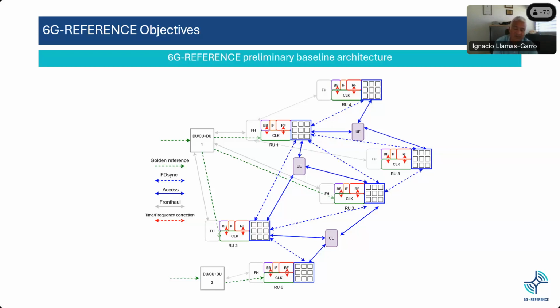Case 3 corresponds to radio units 2 and 6 at the bottom of the figure that coherently transmit to one user but are attached to different central units, which may happen often in a densified cell-free deployment. In all these cases, the aim of synchronization mechanisms is to provide time alignment at the radio unit's array planes. Better time synchronization using full duplex synchronization can relax processing mechanisms due to potential time difference of arrival to the different users and can further enable coherent transmission for radar sensing.